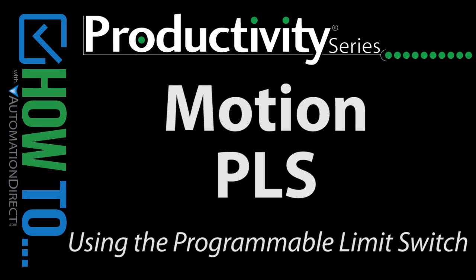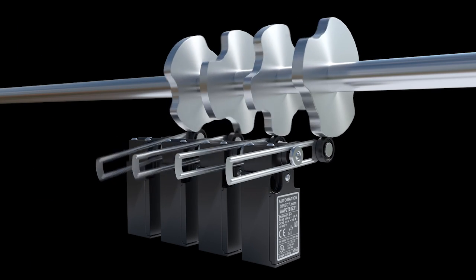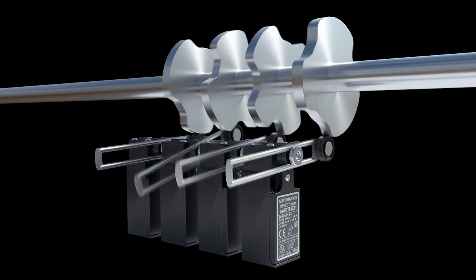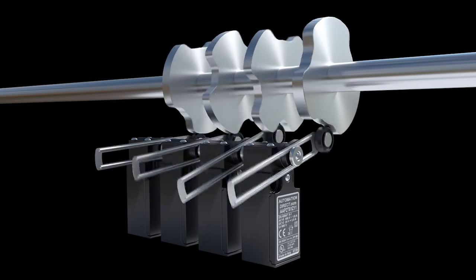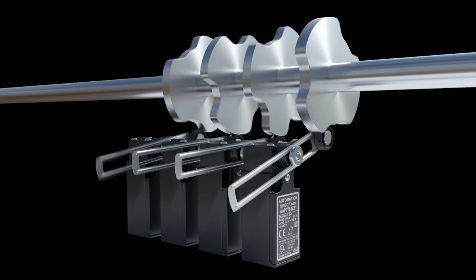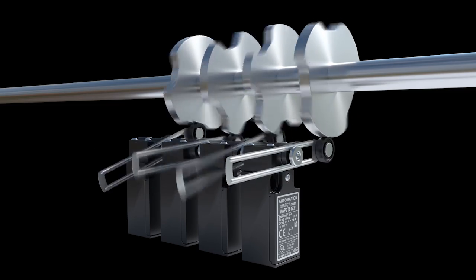The Programmable Limit Switch instruction works just like a mechanical rotating cam with limit switches, except you can control the shape of the cams in real time. And since it runs on the high-speed input module, or HSI module, it's completely independent of the processor load or scan time, so you can always get accurate timing even with high-speed inputs.